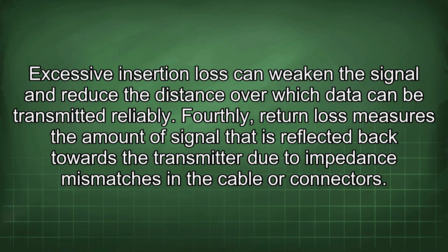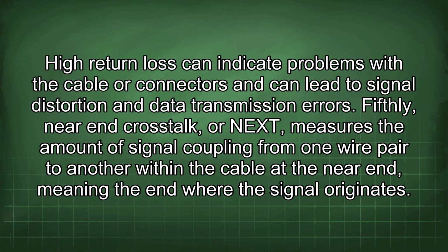Fourthly, return loss measures the amount of signal that is reflected back towards the transmitter due to impedance mismatches in the cable or connectors. High return loss can indicate problems with the cable or connectors and can lead to signal distortion and data transmission errors.